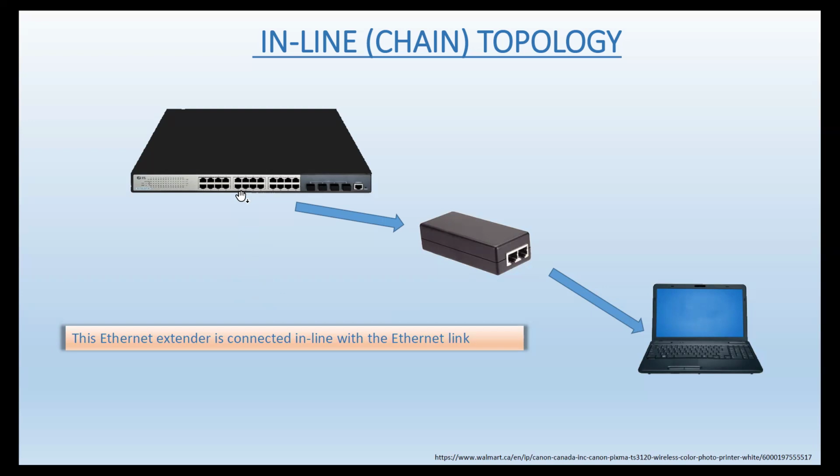And I would say, okay, so here is something like 280 feet from here to here. Okay, and then I unplug that, and I plug in my meter to the other line that goes from here to the PC, where the pull box is on the ground, coming out of the ground. And over here it shows that it's like 50 feet. Well, 290 feet plus 50 feet is going to give me 340 feet, which is more than 328 feet. That's where the problem is.